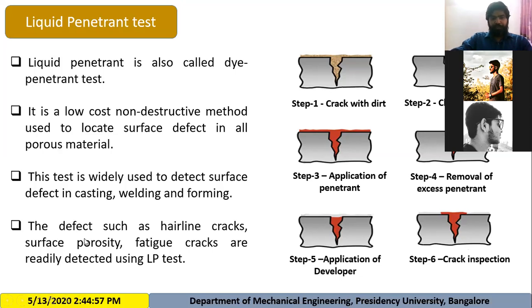So that surface porosity, and fatigue cracks, if there is any crack that exists on the surface due to fatigue, are readily detected using this LP test. LP test means liquid penetrant test. So let us look at the procedure of how this liquid penetrant test works.